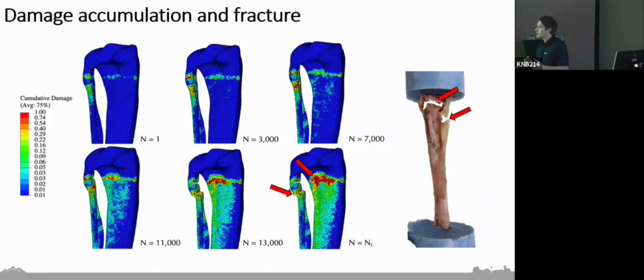If we were truly getting a linear strain pattern going down the axis of the bone, the model should account for that, and you'd see a big fracture going down that long axis of the bone. But on the individual element level, we don't model that. We just hope that it shows up in the end, which it does seem to when we get to that macro scale crack.